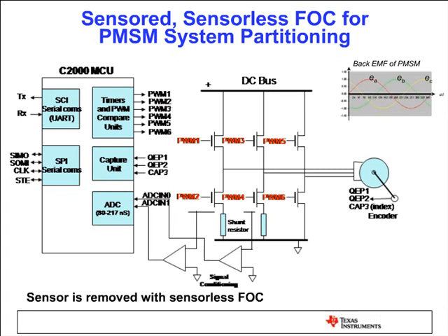Since these are connected low side, we observe voltage pulses when we turn on PWM2 and PWM4. So the voltage across these resistors is composed of pulses, very narrow notches. That's why the ADC should be very fast to sense the voltage level, which means the current level indirectly, within that limited time period, because the pulses are very narrow. And all our C2000 devices can easily sense the current.